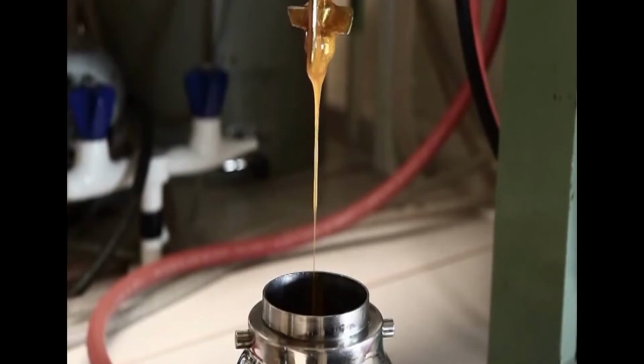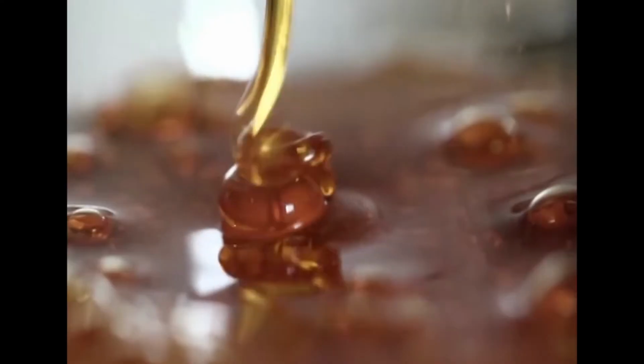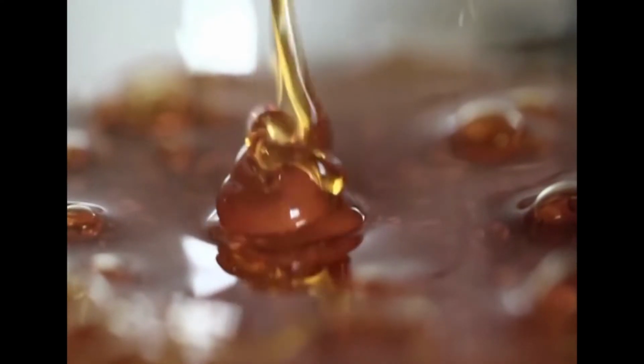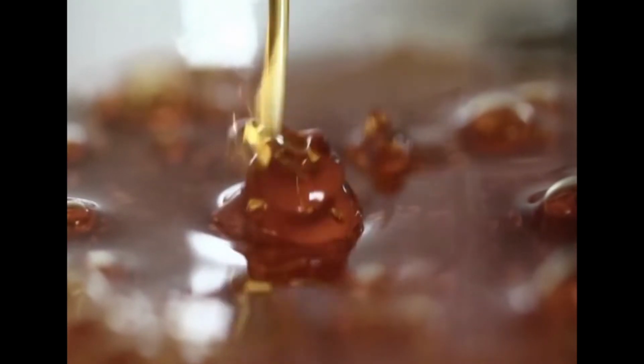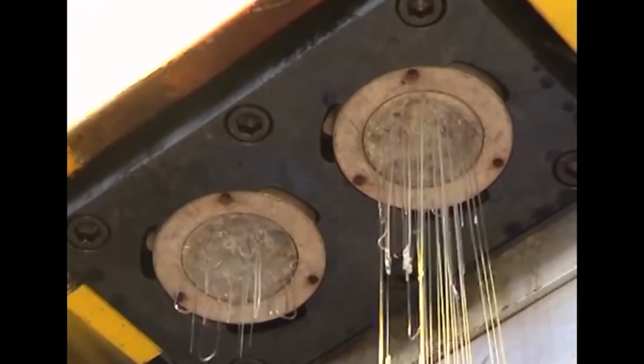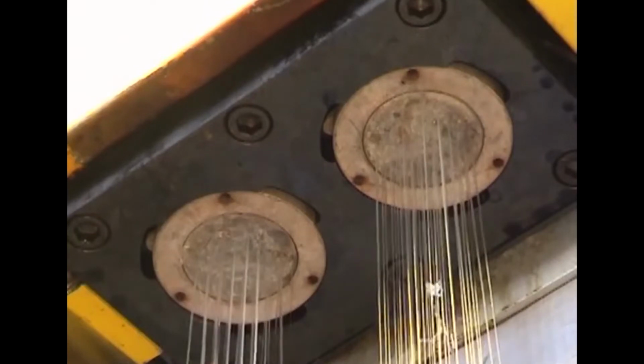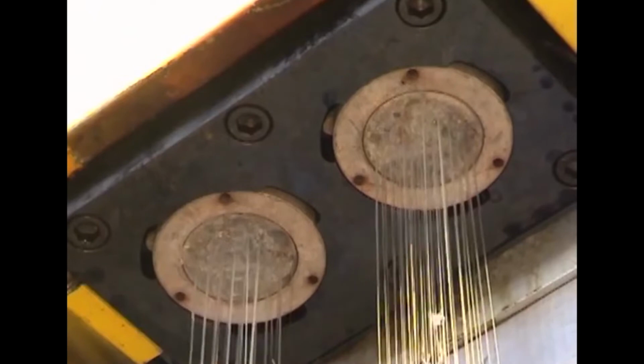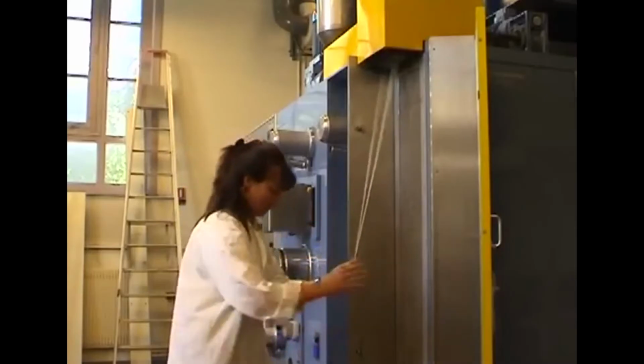In order to do so, the particular polymer is either melted or dissolved in either volatile or non-volatile solvents, and then it is made in the form of a solution. Free flowing of this solution is required, because this polymer is extruded through the holes of a spinneret. It is called a spinneret, which is a small metal plate having fine holes. The polymer in solution form is made to pass through the holes of the spinneret, and then it gets solidified when it comes out, and thus you will get a continuous filament out of it.